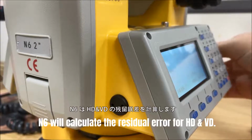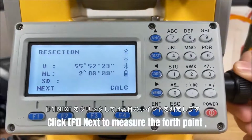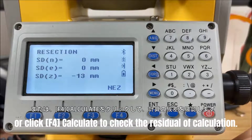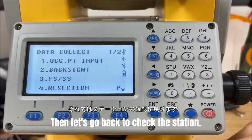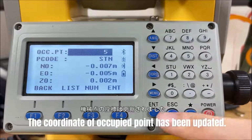N6 will calculate the residual error for horizontal and vertical distance. Click F1 next to measure the fourth point, or click F4 calculate to check the residual of calculation. Press F4 to record the coordinate as station. Then let's go back to check the station. The coordinate of occupied point has been updated.